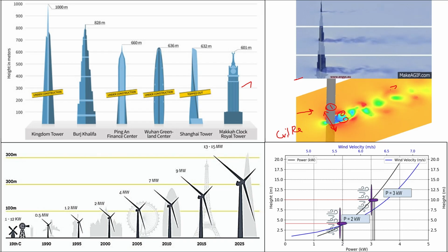Similarly, if you take a high-rise building or skyscraper, we are finding velocity at different heights just to check whether we reach the critical Reynolds number or not. Depending upon that, we design the cross section, that is the size and shape, of the skyscraper at every altitude to avoid reaching the critical Reynolds number. Okay, because only if the critical Reynolds number is reached will there be vortex shedding and vibration damage.